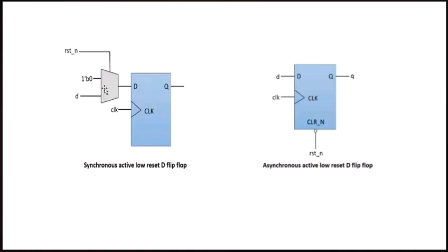When reset is applied, the mux output of the synchronous reset immediately gives the output, but this output moves to Q only when the clock edge comes. That's why we get the output of the synchronous flip-flop at the next clock edge, because the mux is in the data path.